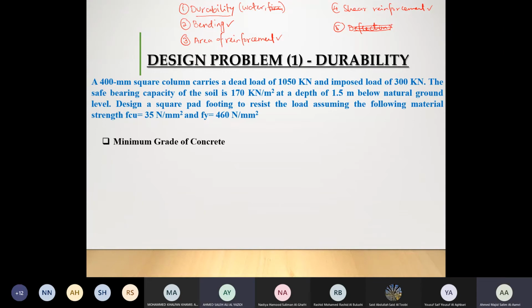So we have a minimum grade of concrete, which is C35. That's the minimum grade of concrete for foundation, if you remember. And then we have minimum cover. We said we don't need to go and check. If we are going to use BCC, it is from 40 to 50. In Oman, we regularly use 50 mm, and we are always going with the BCC. So when it comes to minimum cover and the minimum grade of concrete, these are almost something fixed for you.